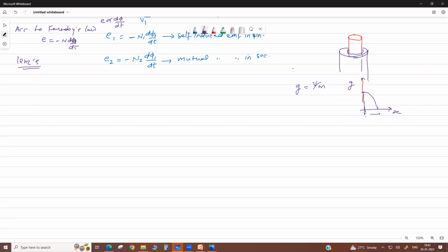So in a high voltage coil, same like if this is your core and you put the HV winding first, high voltage stress will be there. It will deform the core, and electrostatic force will be developed. Just as magnetic force is there in a magnetic field, in an electrical field, electrostatic forces are there due to voltage gradient.